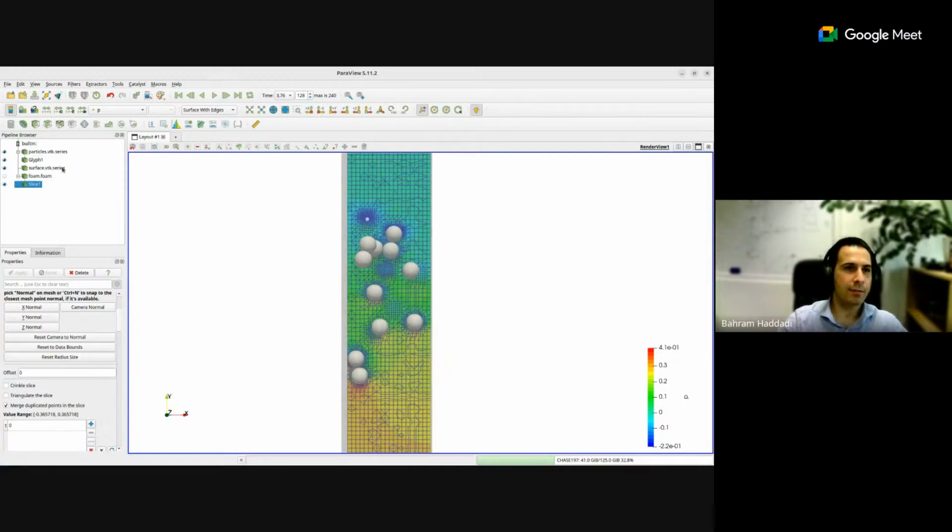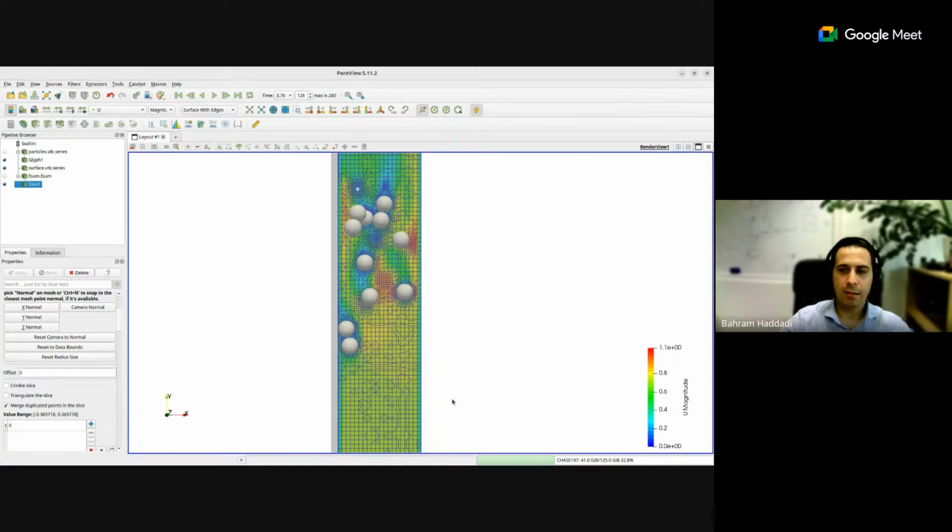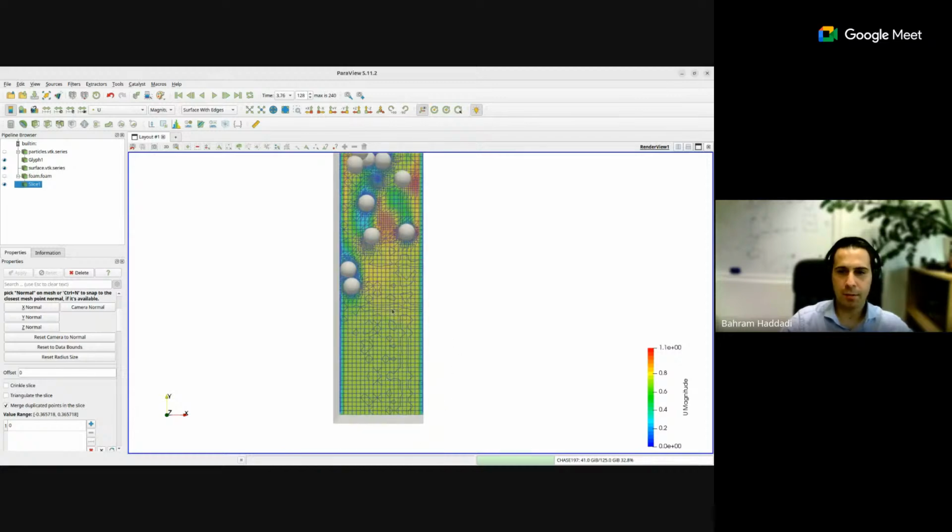As you can see, this is our CFD field. Let me hide that one. The geometry can stay here. For the glyph, it's fine. And let's color it with something different. So with velocity, because we might get a better understanding of what's happening there. So as you can see, the fluid is coming in from the bottom with around, I think, 0.7. That's what we said. 0.6, 0.7 coming in.